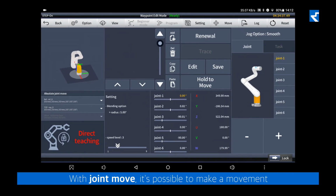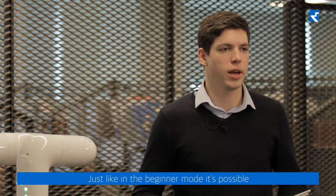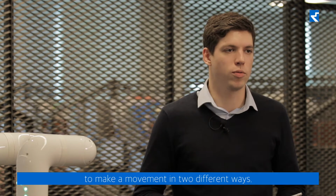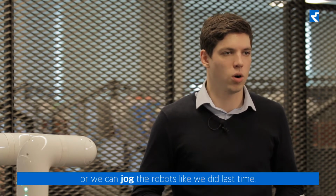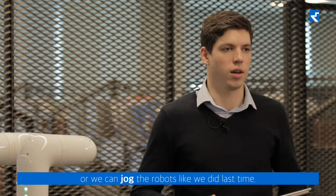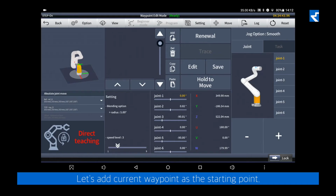With joint move, it's possible to make a movement through different waypoints. We can add and delete waypoints in the middle menu. Just like in the beginner mode, it's possible to make a movement in two different ways. We can either do this by direct teaching ourselves, or we can jog the robot like we did the last time. Let's add the current waypoint as the starting point.